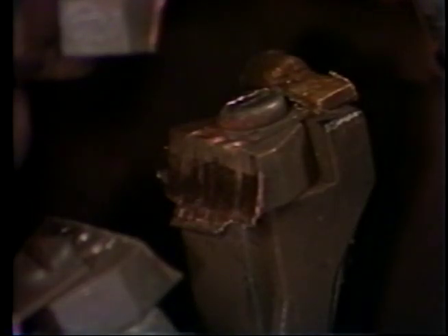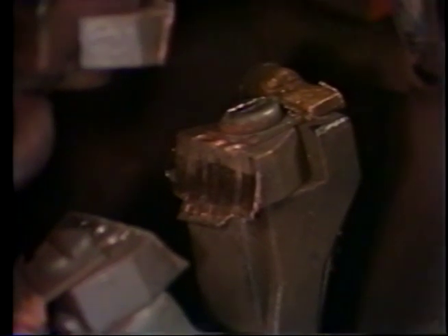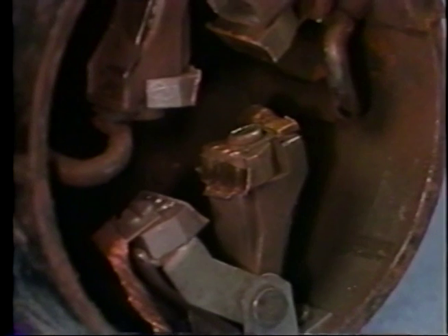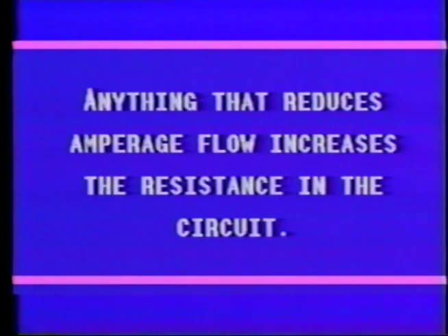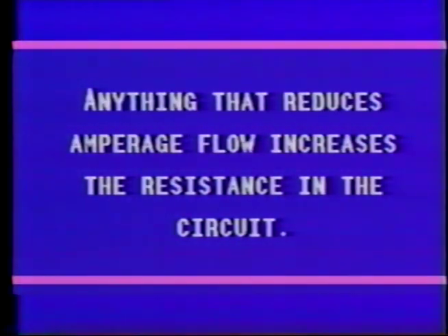For this to happen, there must be increased electrical resistance in the starter circuit. The choices offered by technicians A and B at first don't appear to indicate extra resistance, or do they? Poor commutator or brush condition reduces the contact area between the brushes and the commutator surface, effectively reducing the amount of current that flows through the starter. And anything that reduces amperage flow increases the resistance in the circuit.